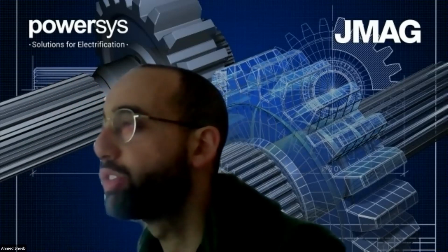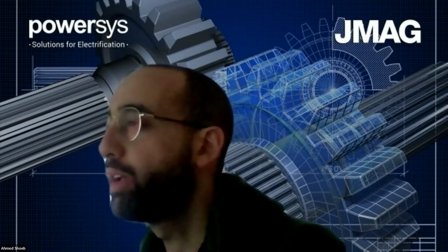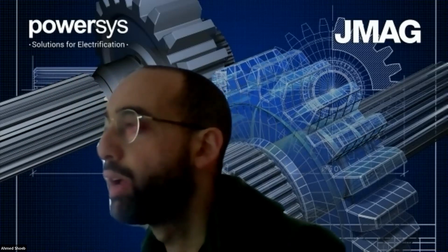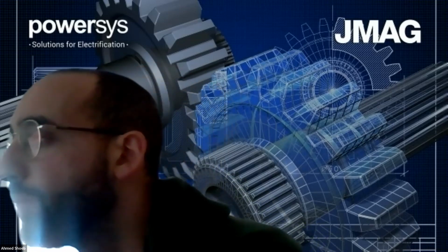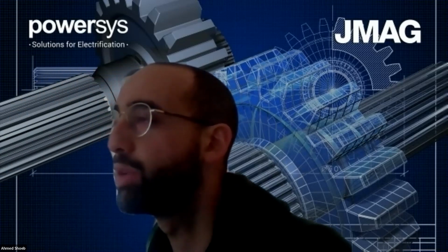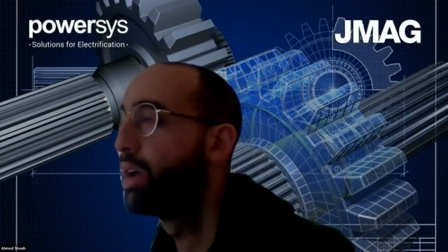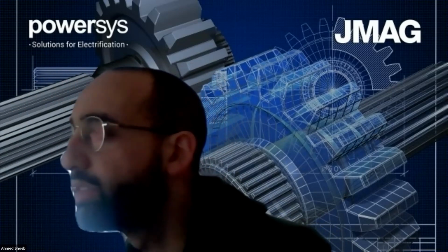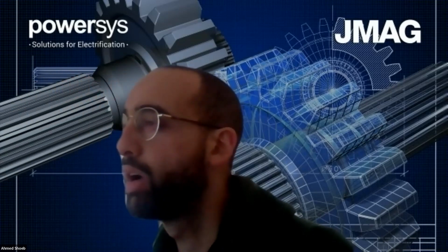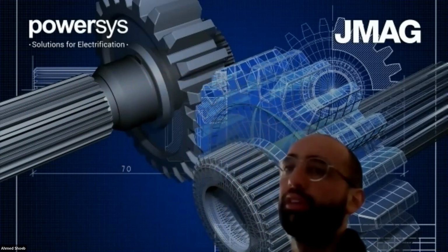I also have questions regarding map calculation. In the case of a traction motor, voltage utilization is a matter of concern. There are trade-offs between point torque capability and flux weakening capability to find the optimal point in the circumstances. The phase advance shall be decided during large-scale design exploration. What was your strategy to deal with this?